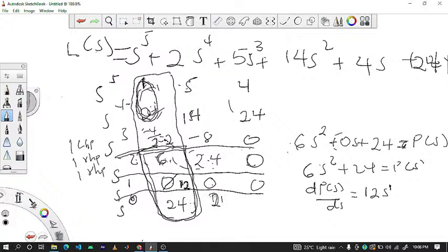So you have 2 here. But there was no sign change, and this came from solving using special cases. The solution is on the imaginary axis. So we have 2 on the imaginary axis. Your final answer will be 2 on the right half plane, 1 on the left half plane, and 2 on the imaginary axis.